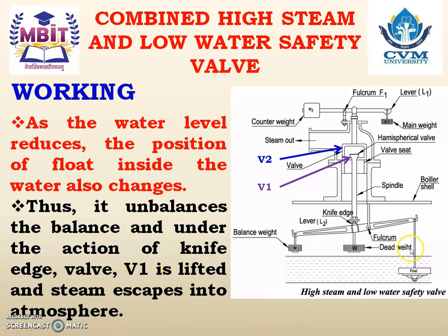So when the water level reduces, the float will come down, and due to that it will lift the spindle, and as it lifts the spindle, it will lift valve V1, and valve V1 will be opened, and due to that steam escapes into the atmosphere.